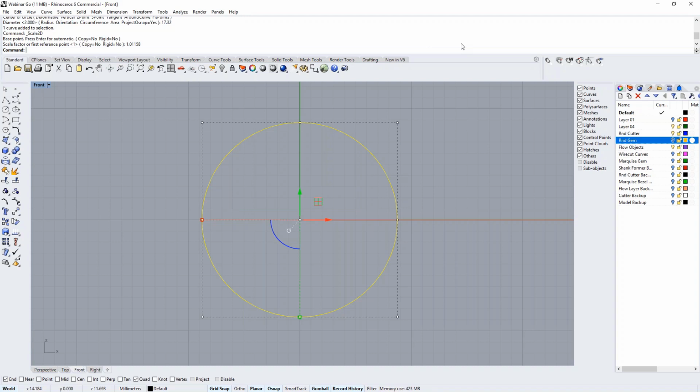So my goal is to have it come out just slightly under. And I think that's a pretty good practice. But with bezels, for example, we're going to see this in a little bit, I usually offset the gem size by 0.4 millimeters to create a bezel, depending on the size of the bezel. But that works pretty good. And I find that about a 3% scale factor works a lot better to ensure the gemstone fits there.